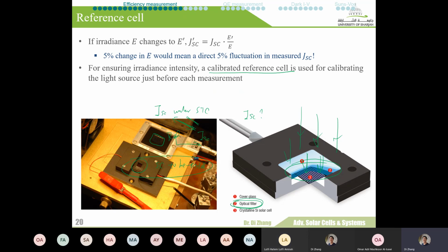But given that the solar cell we're using here is very small, what we could do is provide very good conduction with a very thick layer of wires, and measure, for instance, the resistance of the solar cell. Then you can separately measure the resistance of the wires and compare between them.